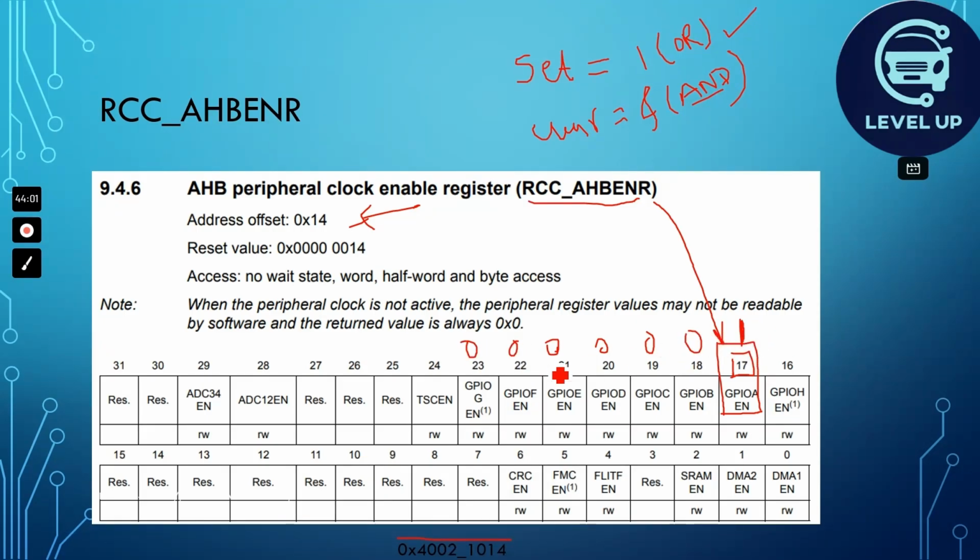So we are basically making a mask value. Okay, so what is mask? Mask is the value where we put our interested bit as 0 or 1 as set or clear accordingly, and the remaining bits should be untouched, and we just use it inside AND or OR operation. So likewise this will be 0, all of this will be 0. So what will be the mask value then? Above 4, in the hex value we will calculate 0, then this is also 0, then it is also 0.